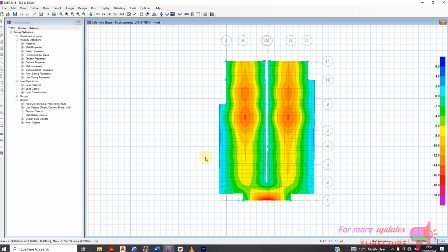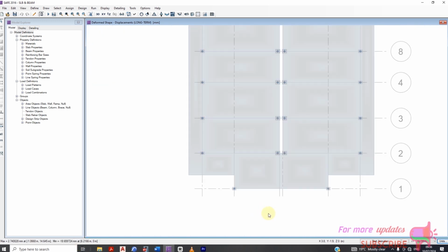You can see this one is not okay at all in terms of deflection. So if you construct this house with that depth, this is about 6.2, this is about 4, it's the most critical panel. It has failed. All right, you need to check deflection because our maximum deflection is 18 millimeter and the permissible value is about 12 millimeter. So you need to increase the depth of this.